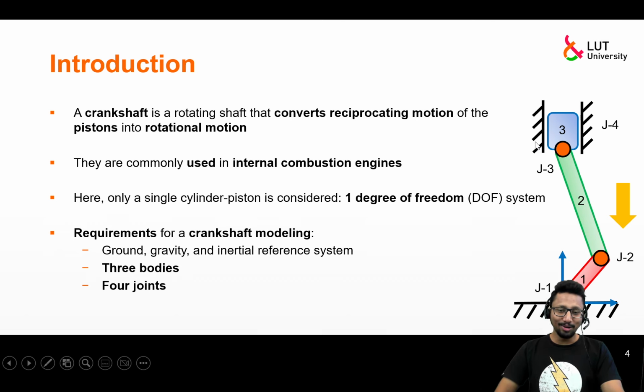So here is the trick. We know from our logic that the degree of freedom is 1. But our mathematics in 3 dimensions is saying that the degree of freedom is coming to be minus 2, which cannot be true, right? So either our logic is incorrect or our mathematics is incorrect. In this case, we know our logic is correct because there is only one motion, only one degree of freedom, one motion which defines the motion of the rest of the system. We know that, and we have seen it already in the sneak peek. So of course, the mathematics is somewhere wrong.